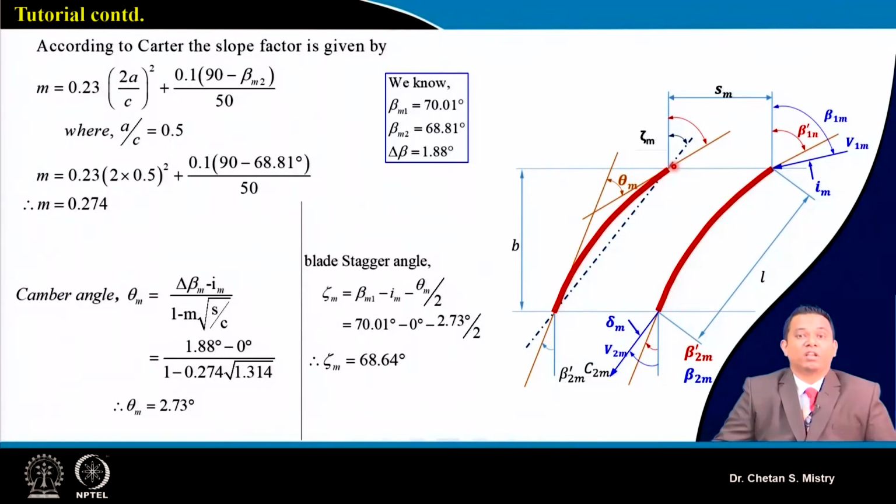And as we have discussed earlier, maybe you bend the plate, and if it is rotating, that also will generate a pressure rise. There is a special requirement of aerofoil when we are expecting our pressure rise in a systematic way, because we have a pressure surface and a suction surface. We have flow acceleration and deceleration on the pressure surface as well as on the suction surface, and that is what decides my pressurizing capacity. Here in this case, our expected pressure rise is low, and that's the reason we will be taking a bend of this plate.